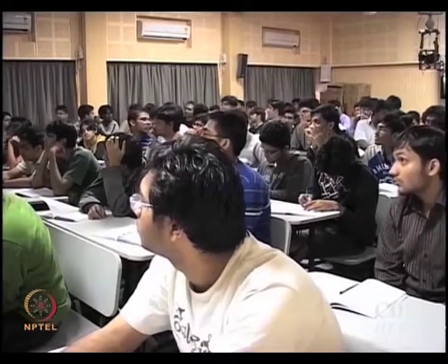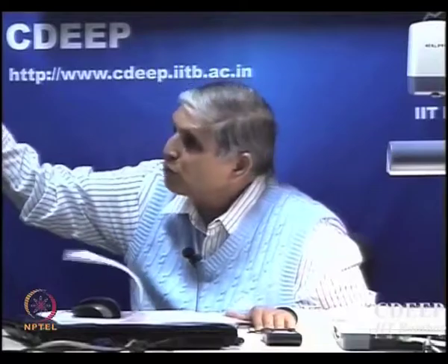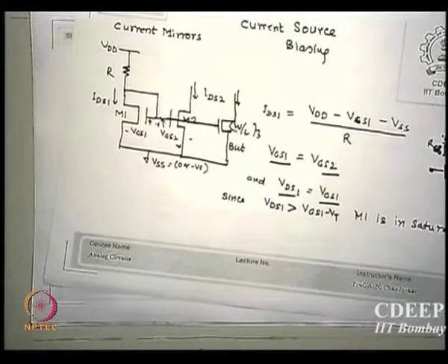These currents ensure the same VGS values. The reference is the first one. The other ones follow, because biasing is done by current now, not by VGS. Current is proportional to VGS minus VT, so I fix the current, I get VGS, which means saturation. Is that correct? That is the way I am doing it now. This is done in integrated circuits, not discrete.